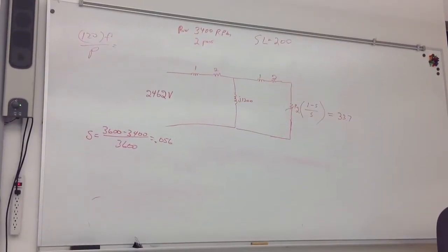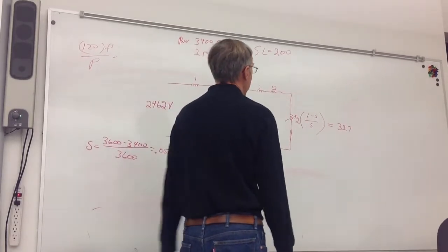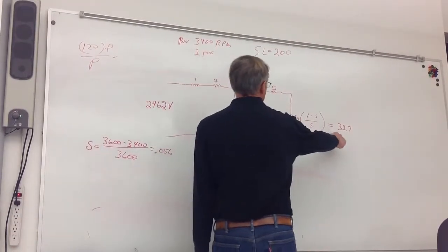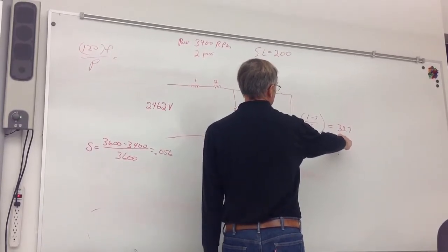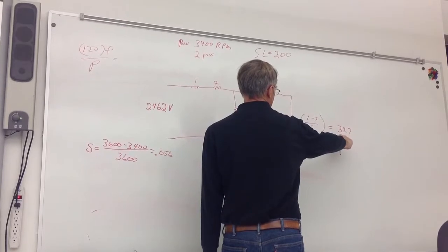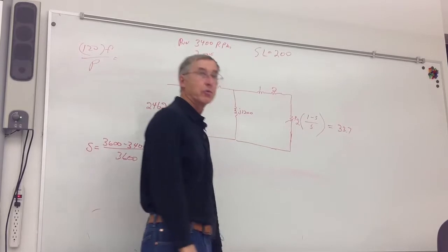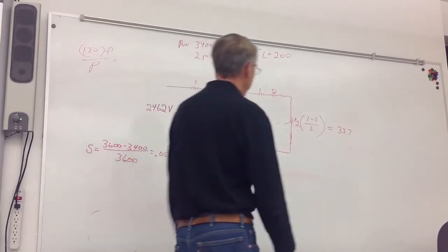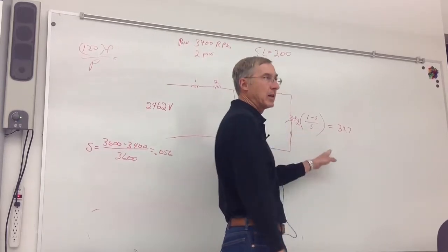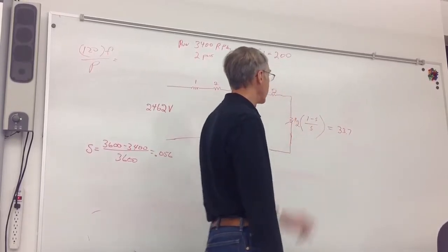Simplify it all into one and find the current coming in, and then find the other current. Is this real or reactive? What angle is this going to be at? It's all real because it's a representation of the real power output of the machine. The only things between here and the shaft are real watt losses, so this has got to be real power.